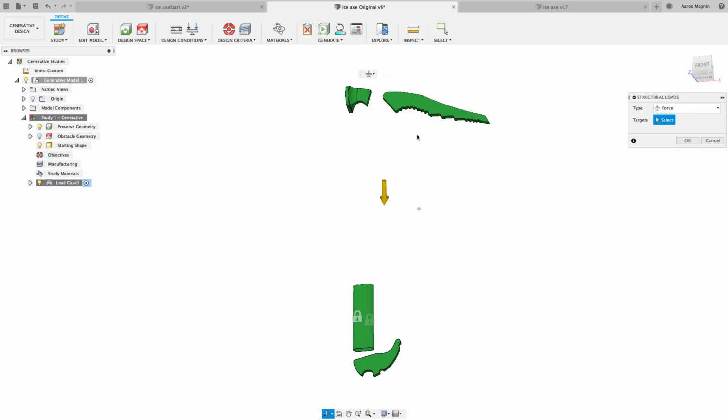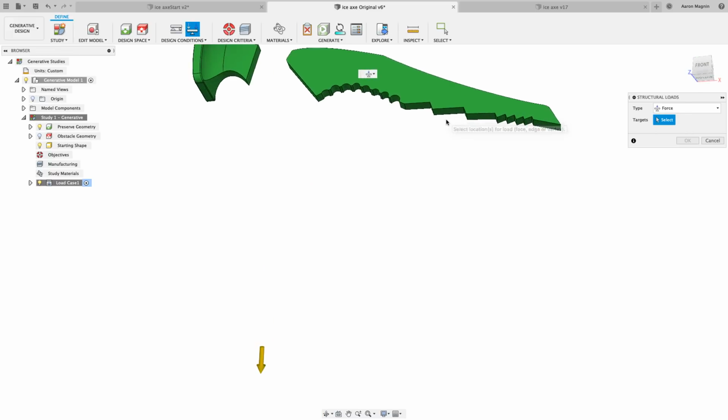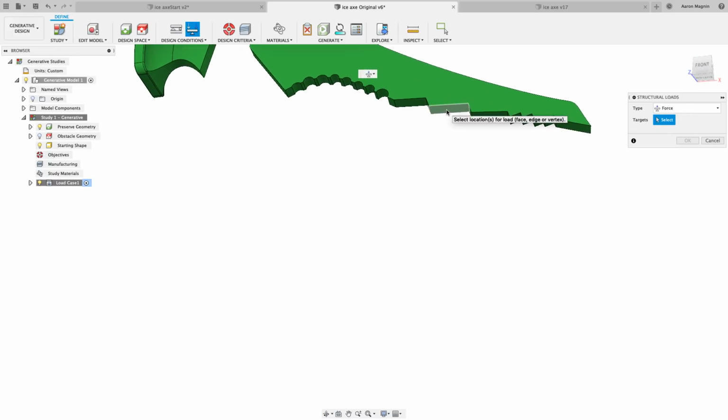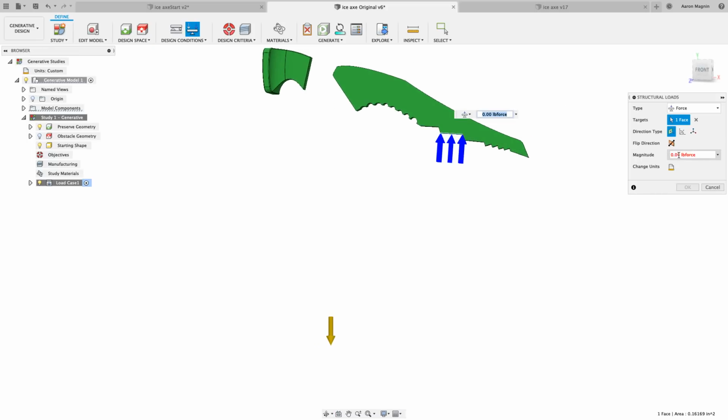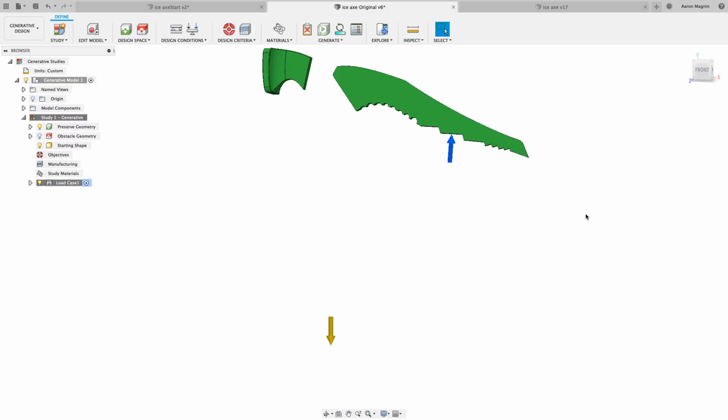And I want to align to what I was using before so that we're looking at this apples to apples. And I'll select that face right there. And this force, the one that I had previously defined, is acting normal to it, so I don't really have to play with direction or anything here. But I'm going to set this at 350 pounds, as mentioned. That was what I found to be the worst case scenario, right? That's the climber and all his gear and all kinds of stuff going on there.